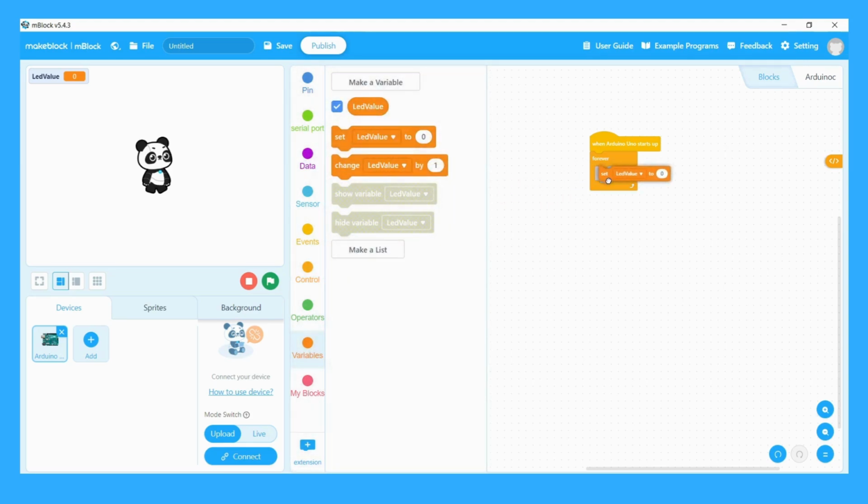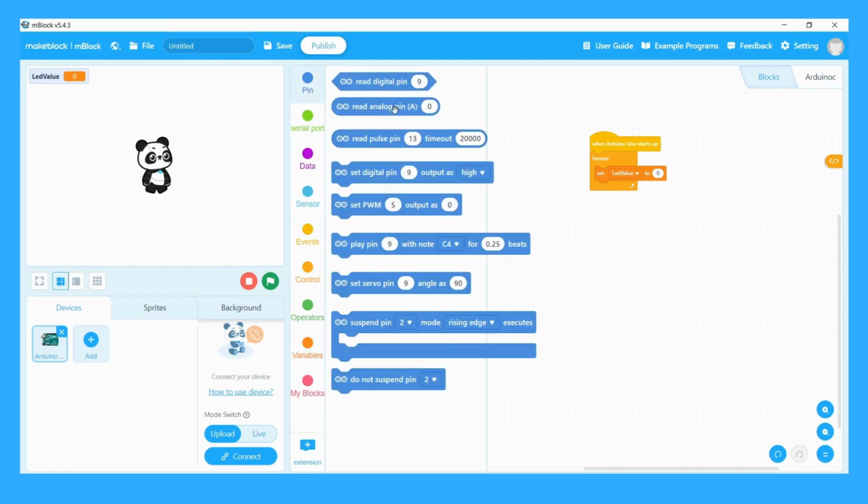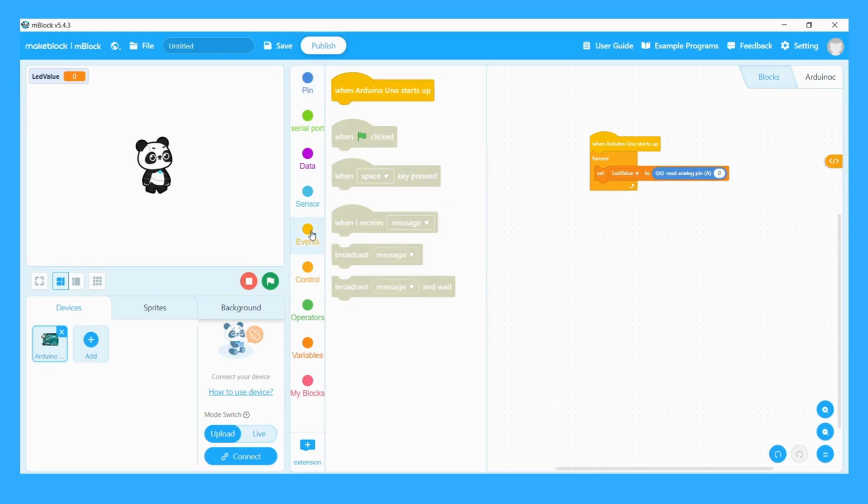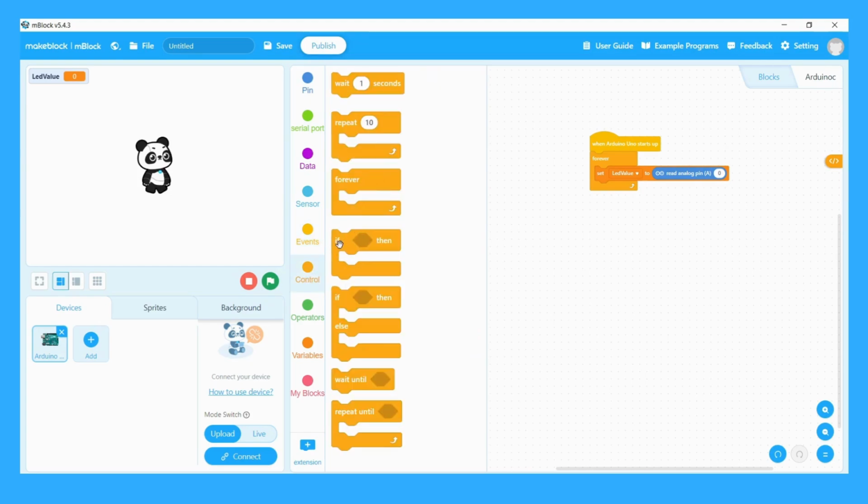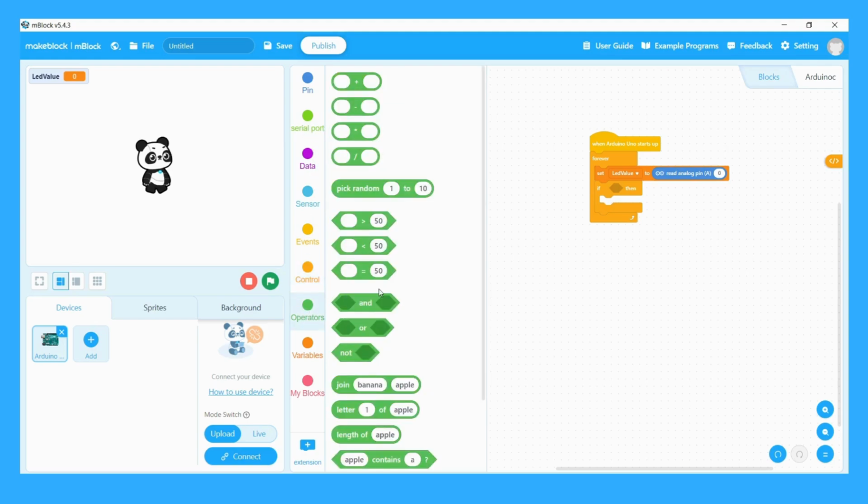First, we need to define the analog pin we will use. In this project, we will use the A0 pin. Arduino will convert the analog information from this pin into a digital value. By dividing the converted digital values into specific ranges, we will decide which digital pin to activate. To ensure equal distribution, I divided it into 200 unit parts. After selecting the required analog pin, I will choose which digital pin will be activated by the digital value between 0 and 200.